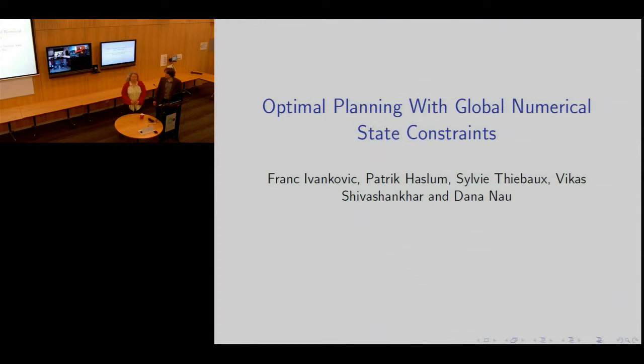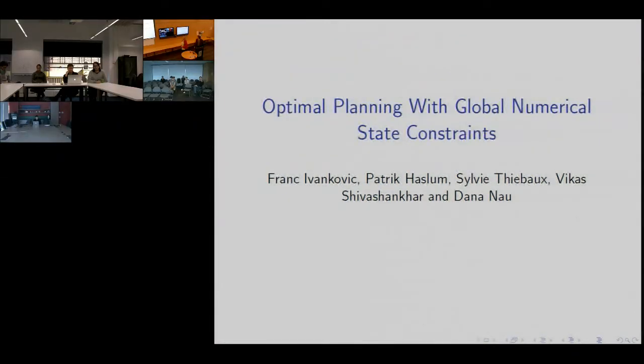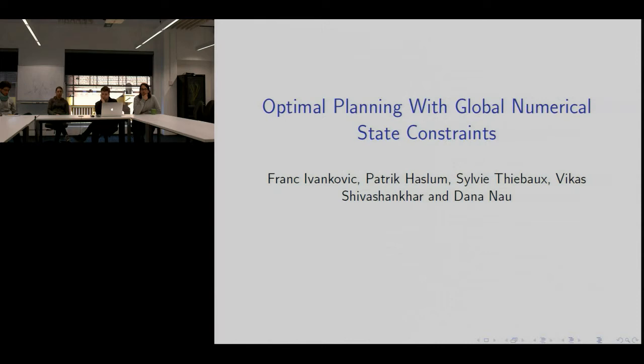So I do have one follow-up question then. I've done some work on this problem on networks that come from the Newcastle area with a local power company, and they were very concerned about the DC model. They were not happy with the DC model, and they felt that in the failure situations that might lead you to reconfigure switches, they would only trust the AC model. And I wondered if you'd done any validation and encountered yourself any problem with this network in failure situations with the DC model.